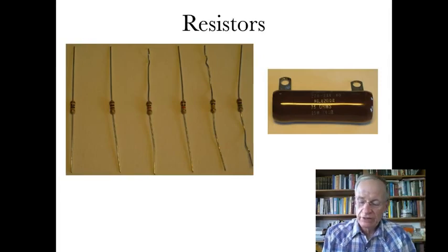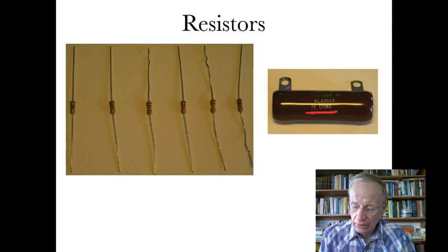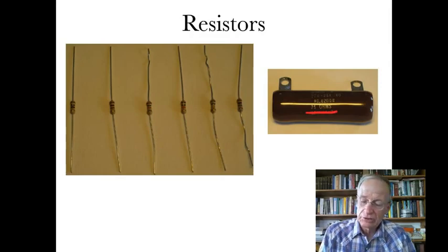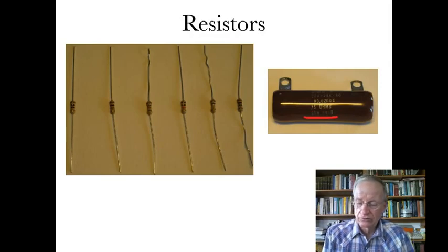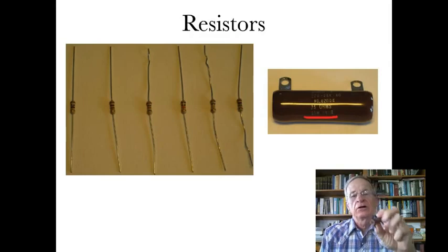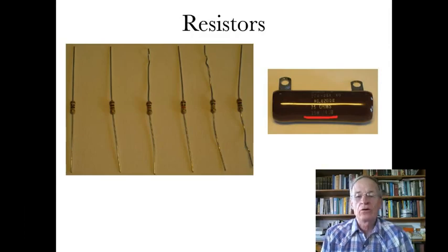And if you look at it very carefully, you can see it says it's 75 ohms, and I don't know if you can see it very well, but down below what I just wrote over, it says it's 25 watts. So this will dissipate lots of power. It turns out it's hollow inside, and that's there to allow more power to dissipate from this. So this is able to put out lots of power.